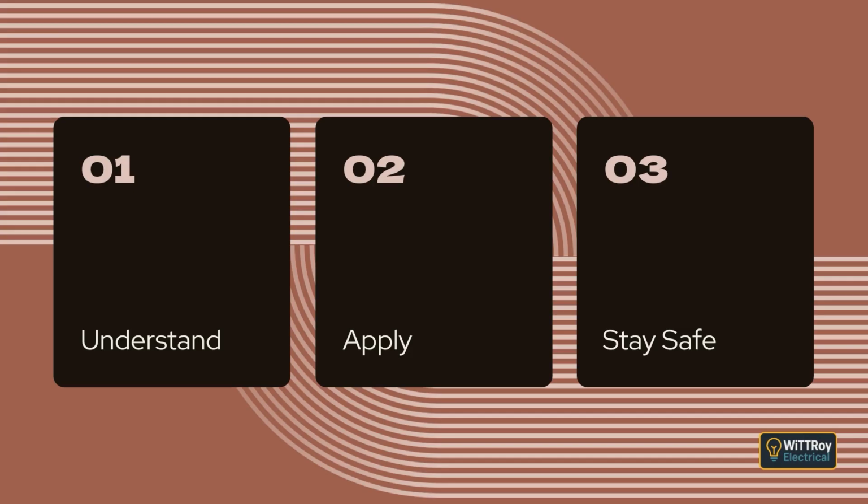When the insulation color of the connected conductors already makes the function obvious, extra marking may not be required. Clause 2.9.4.5 Terminals of switchboard equipment. All terminals on the switchboard, such as for breakers, fuses, RCDs, and similar devices, must be marked so you can tell which active and which neutral belong together.